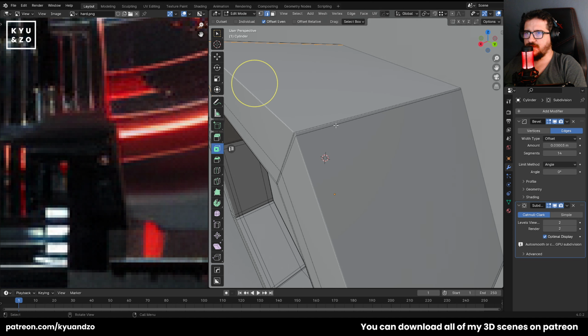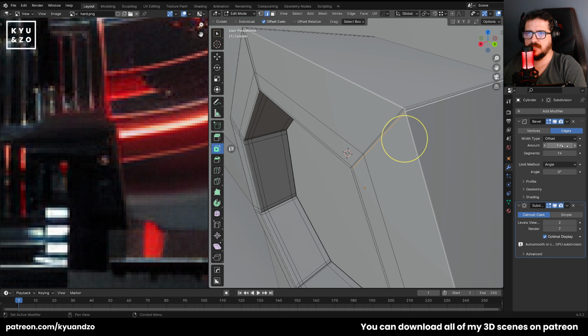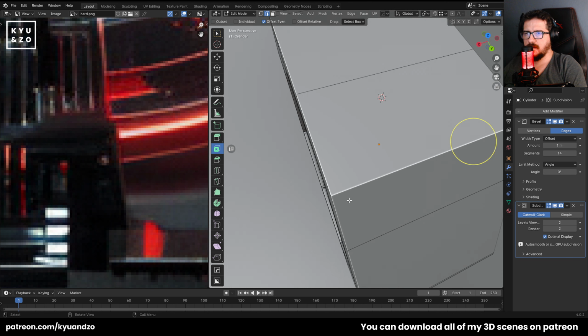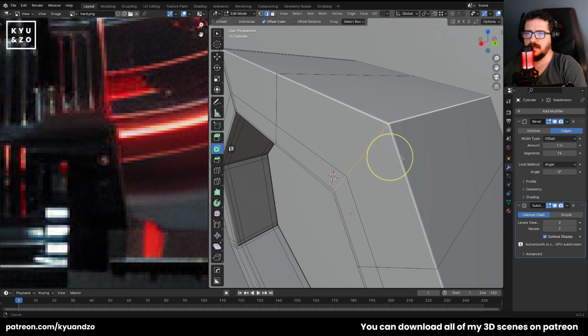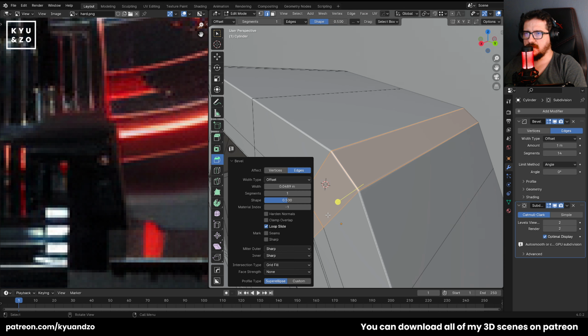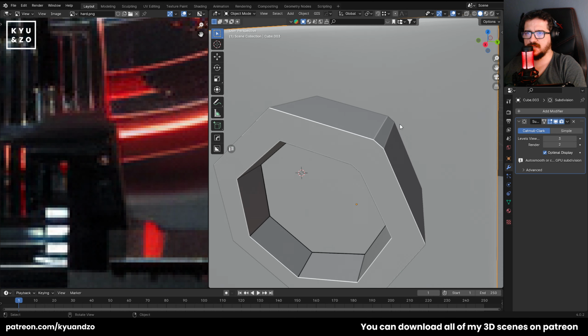So the advantage of working like this is you can make it slide. Just change it to 1. You can just slide it, you can release it a little bit more. And you may say that you don't like something, for example, I don't like this area and I want to have a bevel. It's going to be possible with subdivision surface.